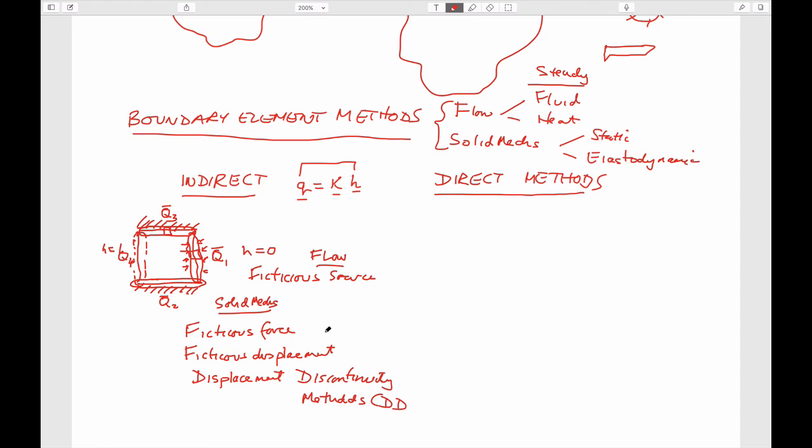And so, in the same way that we talked about, if you could call this uppercase Q if you wanted to, but for the solid mechanics problem, each of these have been defined as basically we solve F equals KU. You could imagine this being defined on an individual element, or you could imagine maybe an element which was this kind of super element that is the whole geometry of the system you have.